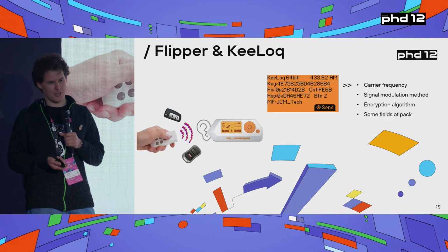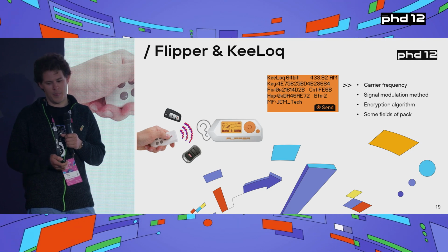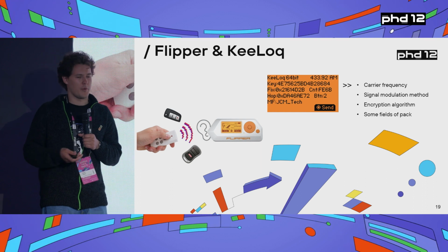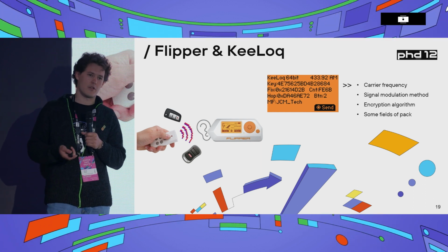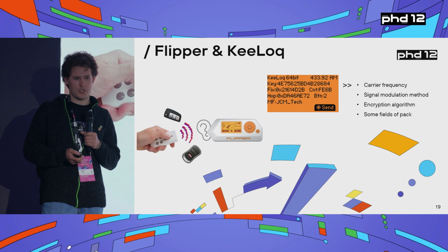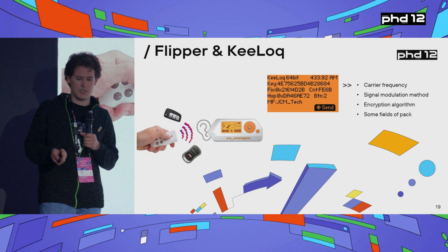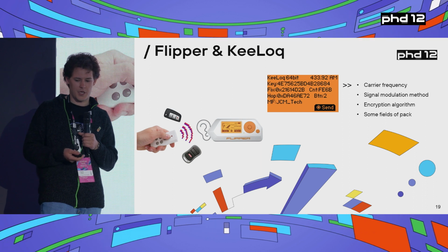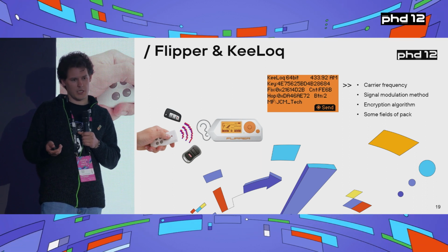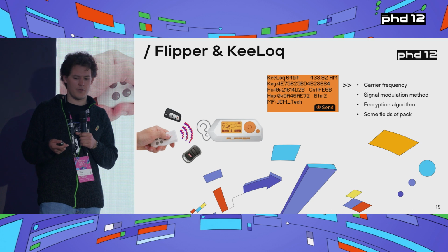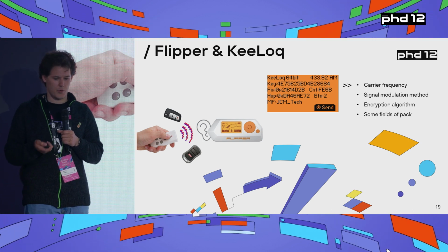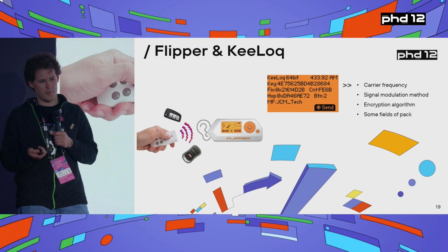I mean, it's not the real deal when it comes to spectrum analysis, but it's good for a bunch of applications like identifying carrier frequency. Also, it can help you identify signal modulation methods. And the picture here also shows that the frequency is 433 megahertz. It's doing amplitude modulation and a 64-bit keylock.